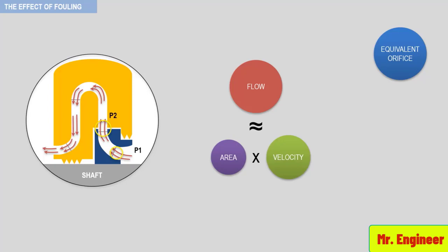By a series of tests and experience, designers have defined optimum relative velocity rather well. Therefore, the resulting inlet and discharge areas will produce optimum velocities and corresponding optimum impeller efficiencies. If, however, the areas were to change and flow passages were to become rough and non-continuous, an impeller performance change would result.